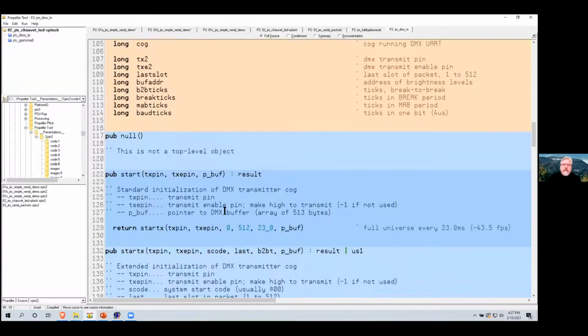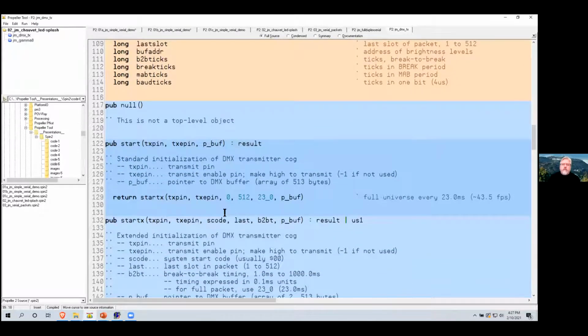But every cheap DMX brick that we've used in these movie props and display things has always tolerated short universes. And my own custom code that I use on the P1 and now on the P2 can detect a break that comes at an unexpected time, and it restarts everything.